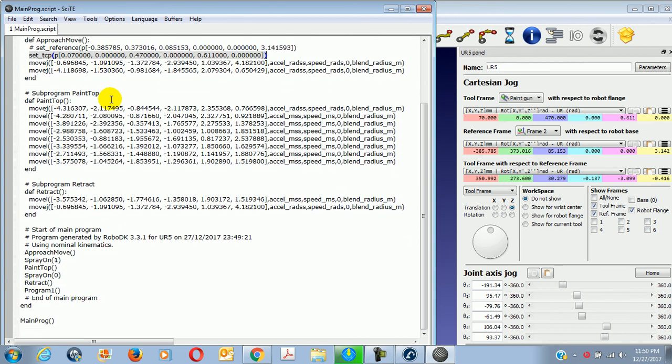That is what makes up the actual robot program. So such a robot program can be designed and simulated inside a simulator and then automatically generated and then downloaded to your robot to test, instead of directly teaching from the teach panel.